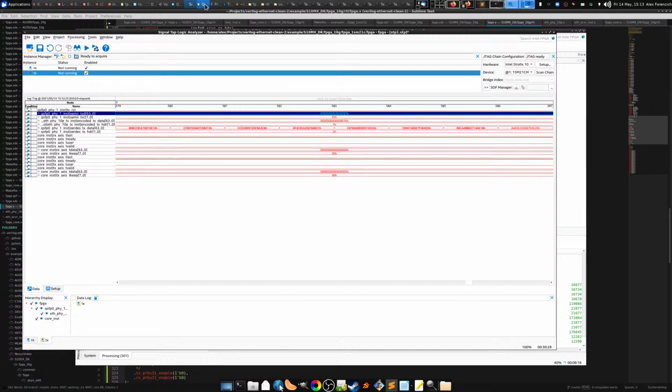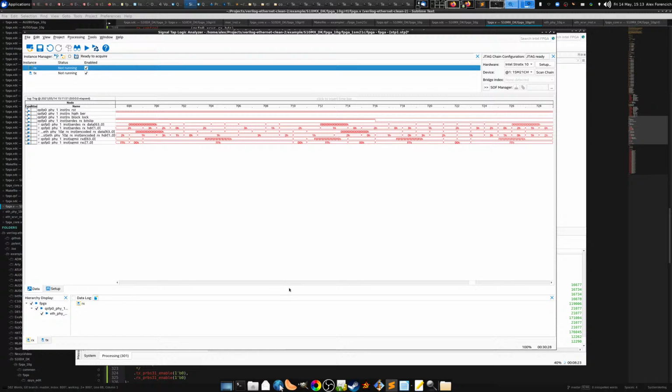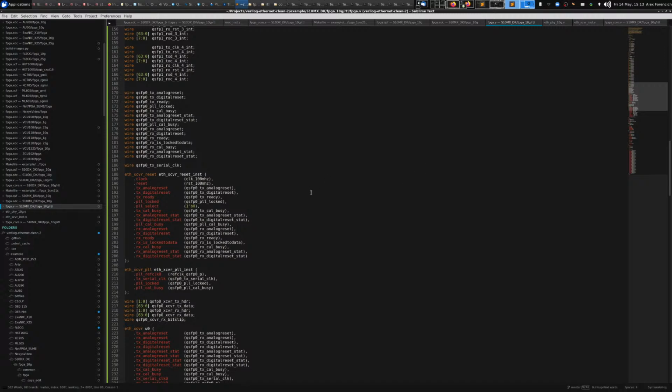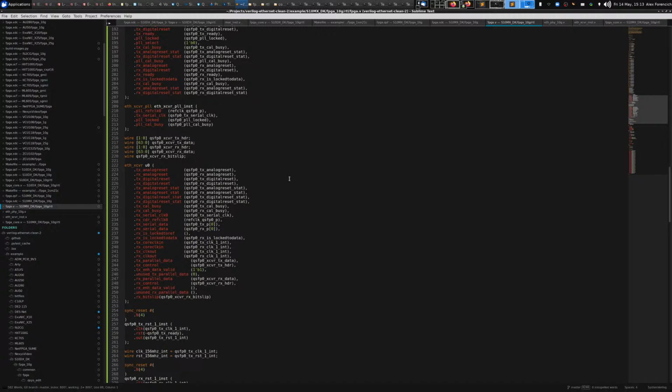Okay, but the question is, what is going on on the receive side? Obviously, something is not happy. The problem is that I'm not sure what it is at the moment. So the module was released from reset. The transmit side is running. The ref clock is hooked up. TX and RX, those are connected. Lock to ref, lock to data, that's right. TX core clock in, RX core clock in, that looks fine. TX parallel data, yep, that looks fine. Data valid, TX parallel data, yeah,